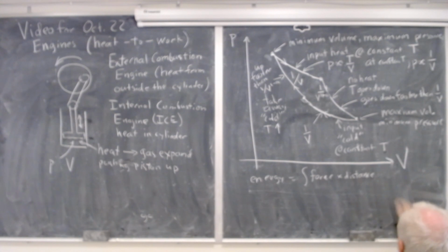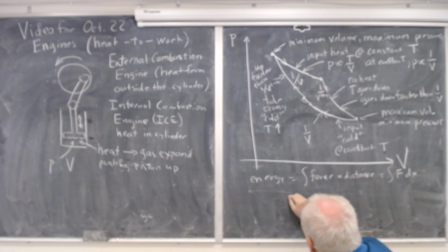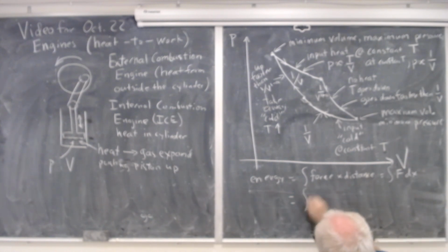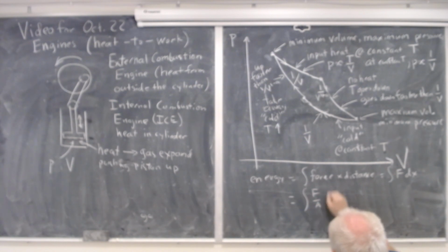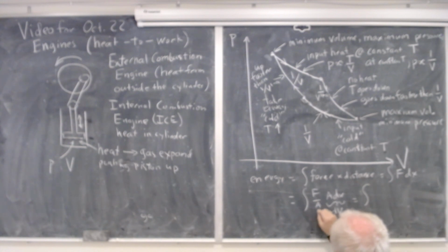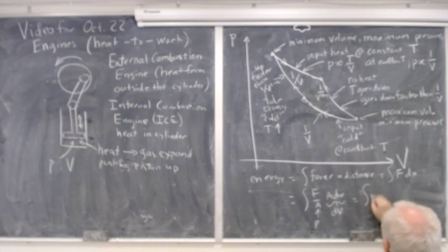So it's the integral of F dx. But pressure is force per unit area, so it's the same as the integral of F over A times A dx. But that's dV. So it's the integral of P dV.